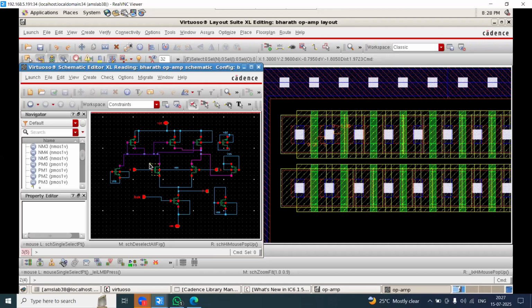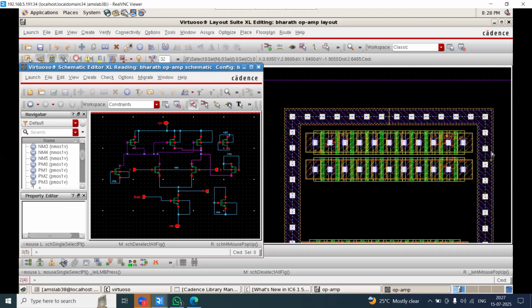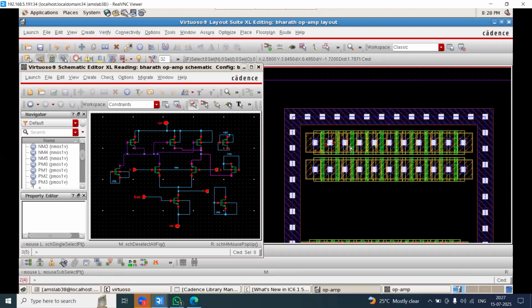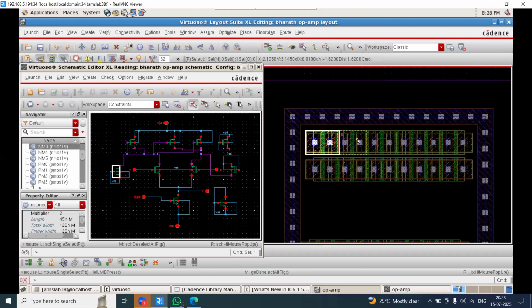Yes, sir. You won't be using dummy devices. If we use dummy devices, we need to add them in the schematic. In order to avoid that, we use filler cells. Filler is a dummy-like device which has continuous ported devices. Sir, here we can't use a stack dummy? Here we can use it, but this much area we can. This is for practical, temporary purposes only.